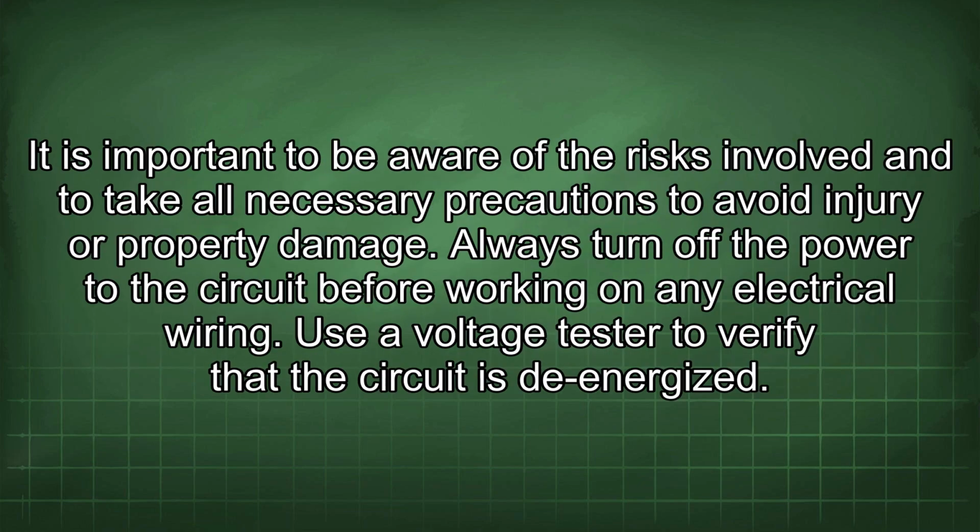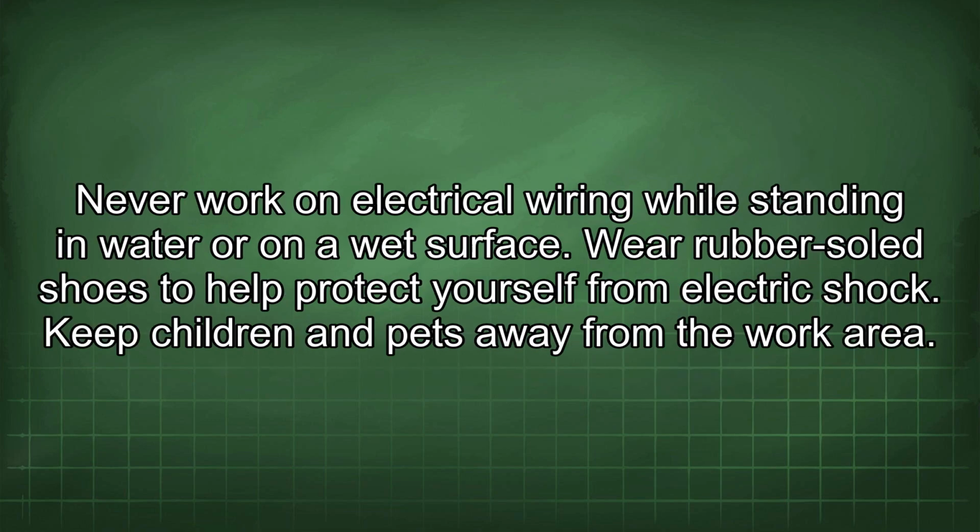It is important to be aware of the risks involved and to take all necessary precautions to avoid injury or property damage. Always turn off the power to the circuit before working on any electrical wiring. Use a voltage tester to verify that the circuit is energized. Never work on electrical wiring while standing in water or on a wet surface. Wear rubber-soled shoes to help protect yourself from electric shock.